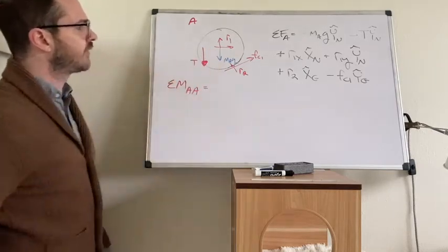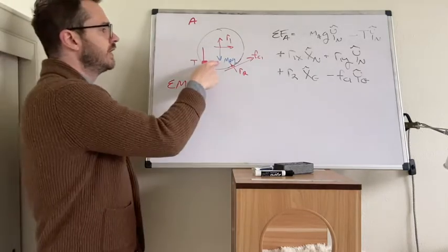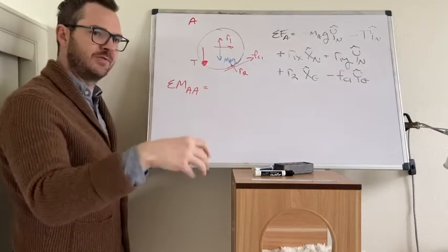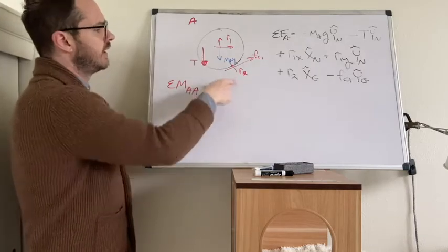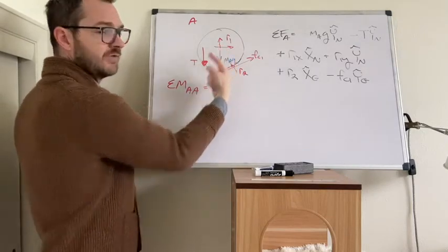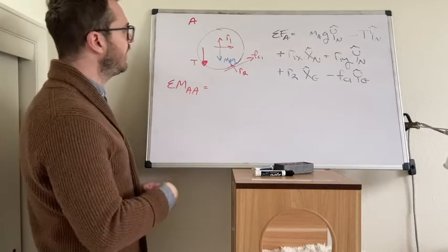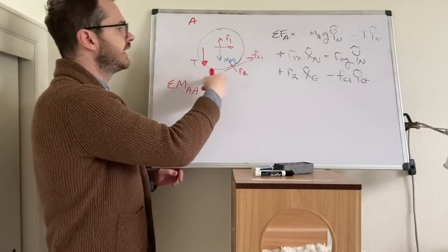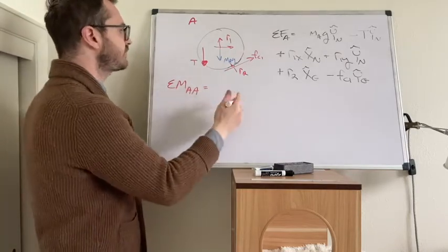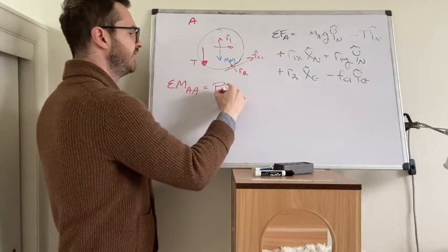And then looking at the diagram, which of these forces even create moments about the center of mass? We know by definition gravity does not. The reaction force R1 is acting at the center of mass, so there is no moment arm. The reaction force R2 actually points towards the center of mass, right? So R2 creates no moment. All that leaves is the tension and the Coulomb force, right? Those are the only ones that leaves. So let's say this is P, the position vector.